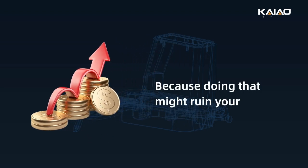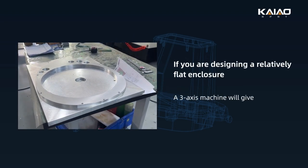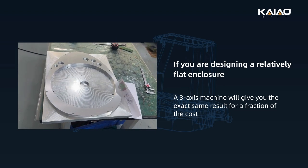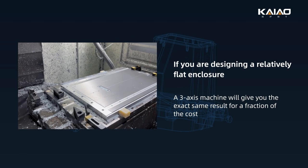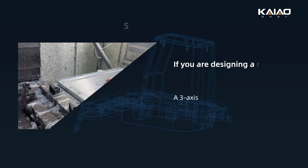First, it's a massive hit to your wallet. 5-axis machines cost a fortune and require highly skilled, highly paid CAM programmers. If you are designing a relatively flat enclosure, a mounting bracket, or simple panels, a 3-axis machine will give you the exact same result for a fraction of the cost. Using 5-axis here is just paying a massive premium for technology you don't need.